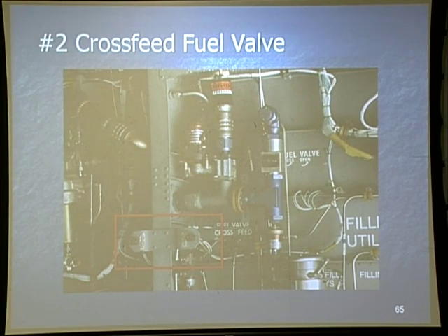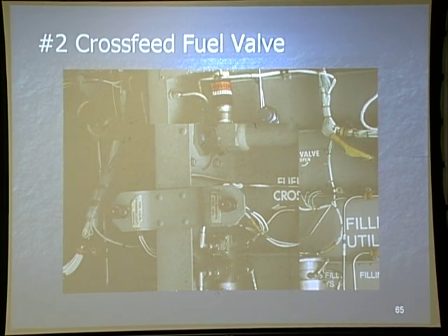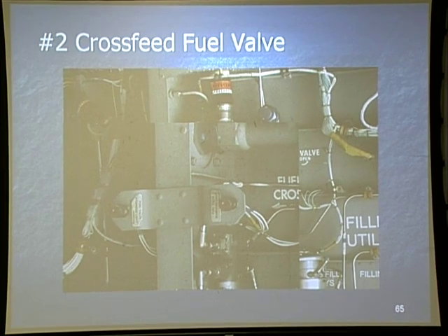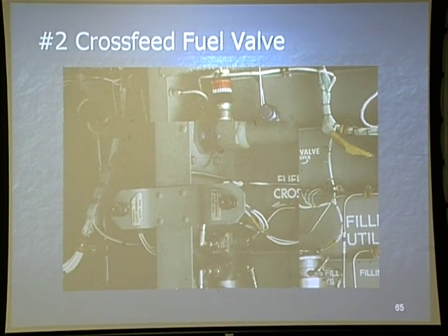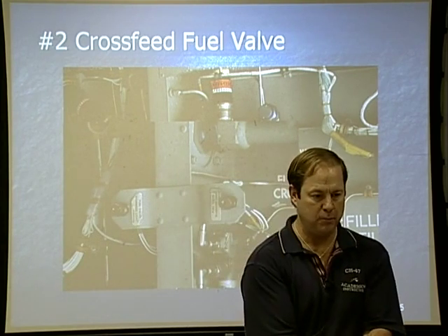Any questions about that? Okay. And there's a close-up of the lights. And they're going to correspond to their individual valves. Keeping in mind that, again, they're only telling me that that valve has transitioned. They haven't told me whether it's closed or open. How do I know whether it's closed or open? I can physically read closed, and in this case I have it open.